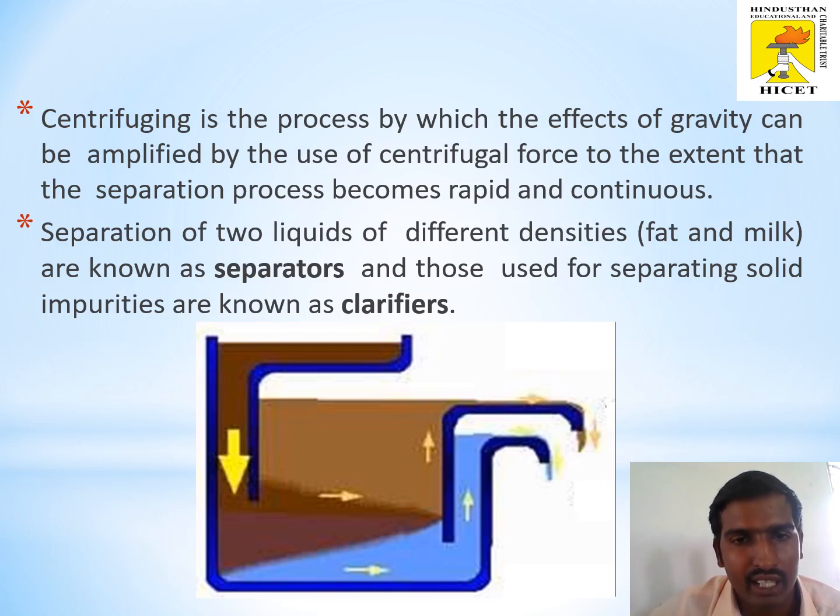Clarifier, it will separate the liquid and the solid dust particles that are present in the milk solution. So that is the difference between the separators and clarifiers. And in the centrifuging process, the effect of gravity can be amplified by the use of centrifugal force to the extent that the separation process becomes rapid and continuous.